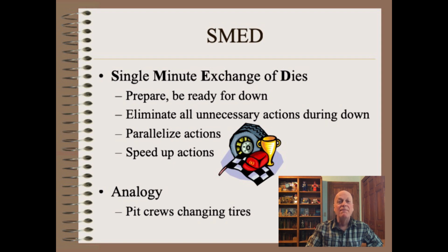SMED is one of my favorite programs and can be especially useful to improve productivity in a manufacturing or rewinding department. SMED was an industrial engineering strategy devised in the 1950s by a consultant to Toyota. The idea is simple, but profound. Grade changes should be as short as possible. Changeovers can be made more quickly using a combination of prepare, eliminate, parallelize, and speed up.